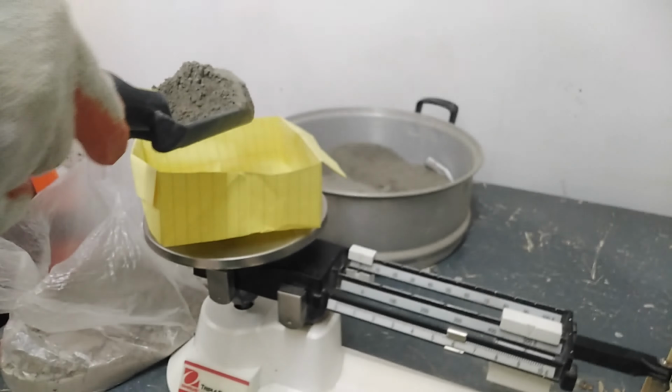Next, leave the sample for 30 minutes. Determine the time of setting. Using the initial Gilmore needle, hold the needle in a vertical position and lightly apply it to the surface. The tip of the needle should be on top of the sample.